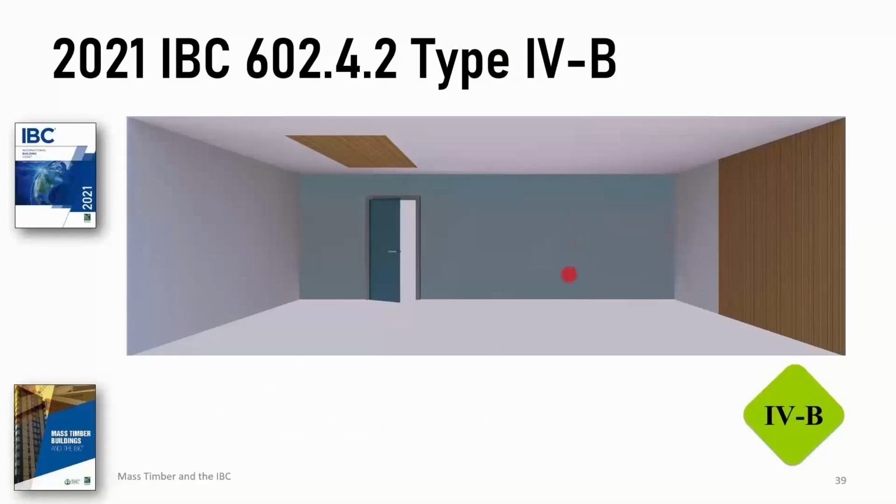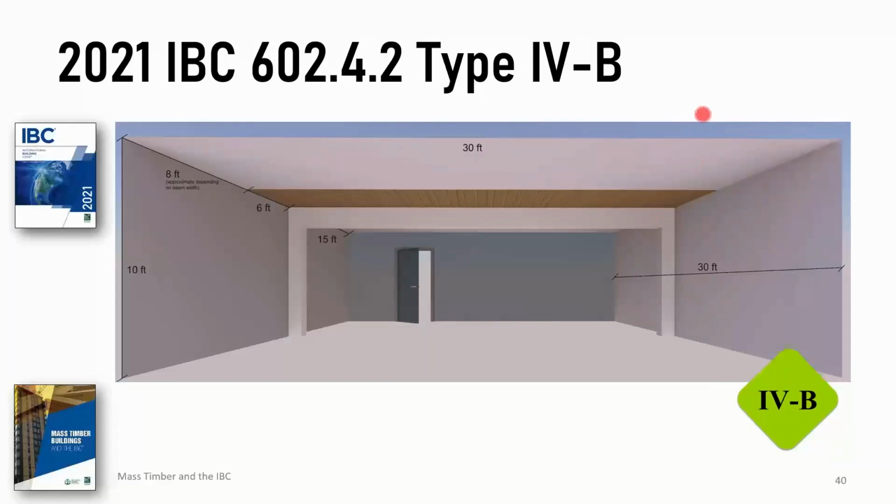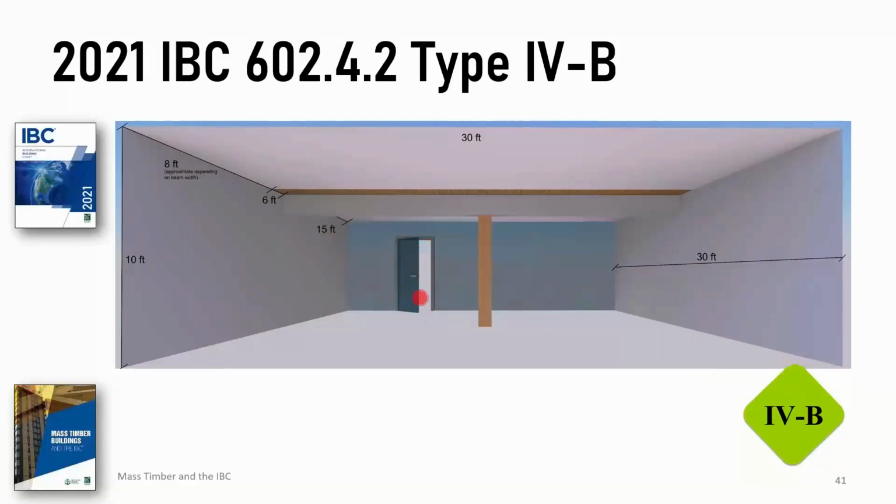So here's the combination. These would have to fit into that formula. Actual exposed area over allowable and so forth. Actual over allowable for the wall. You add them up. And this is showing just an exposed ceiling panel next to a beam. That's a structural beam that is covered, so it is integral to the ceiling, floor ceiling, and the area of this beam would have to be counted. The area of these columns would have to be counted in the calculation. This could be exposed without adding to the area of exposed walls, for instance. It could be exposed.